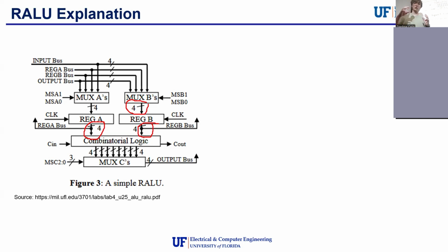What you're going to end up drawing is all of your muxes with all the lines going in, all the lines coming out, all of your select lines. Draw all of your logic gates, your ANDs, your ORs, your NOTs, etc. Draw out basically all of your signals for the functional block diagram and actually think out what it's going to look like. Either you can do it in Quartus first and then draw afterwards, and you're going to have a headache when it doesn't work in Quartus, or you can draw it first and then build it in Quartus, and then everything should work.